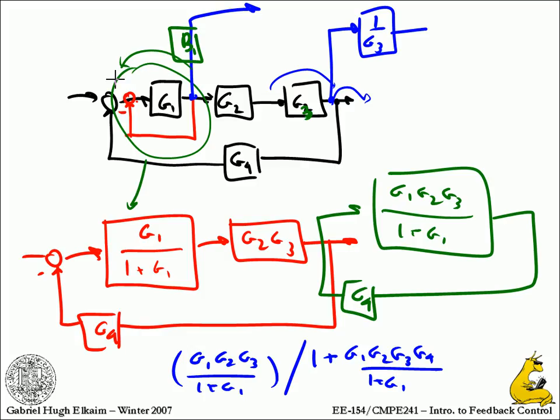But then you have to be careful, because that doesn't really help you unless you then move it across outside of the summing junction. Whenever it gets confusing, just label the signals and work it out algebraically. You can do it by block diagram algebra like I did here, but when you start having these weird pickoffs, if they're easy to move, like doing this is easy, I can move that all the way outside of the loop and then I'm okay.